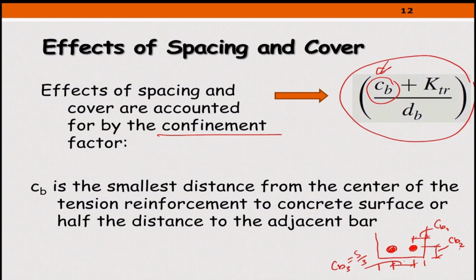It's very important to maintain these values as per the code represented in other provisions, like, for example, the necessity for making sure the concrete cover is 38 millimeter for beams, 40 millimeter for columns.